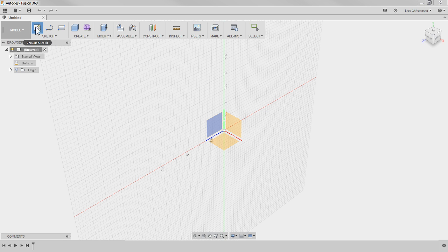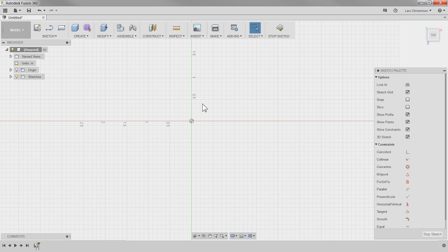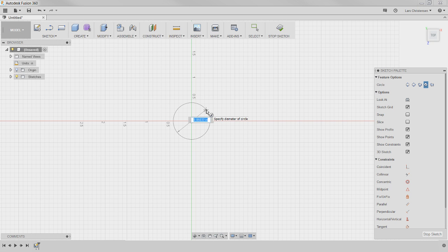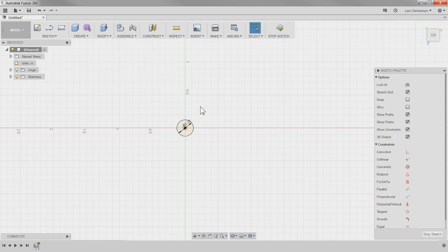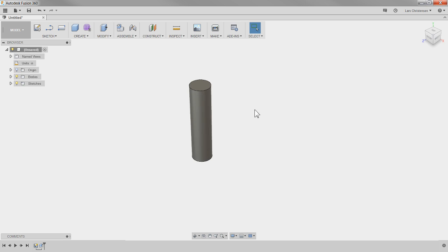So let's start a sketch here. We are in inches, and first of all, I'm just gonna do a circle here, 0.25. So I'm going for a 1/4 thread. So 0.25, and we're gonna say Q, and I'm gonna make it an inch long here. So we have this cylinder, 1/4 inch diameter, 0.25, 1 inch long.